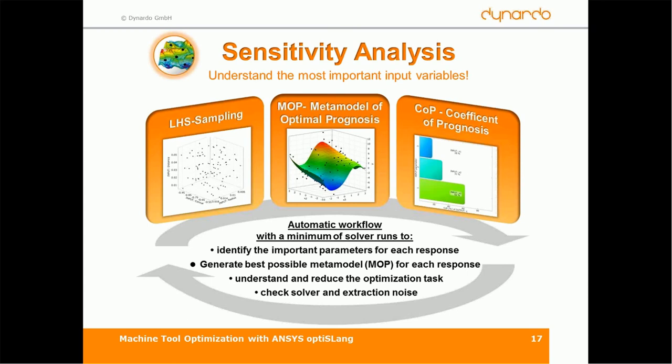This will help us, as we will see now, to judge if the simulation model itself behaves well, meaning that with a variation of the input parameters, we can explain the variation of the responses. If some additional variation appears, this may be a reason of numerical distortion due to a very coarse mesh. We do automatic remeshing, and we collect response values which are not global but very localized results.